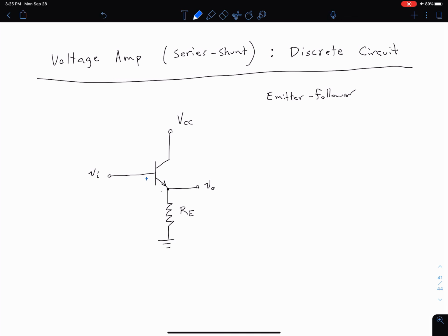So let's label, we have our base emitter voltage here, and notice I'm doing small signal labeling. So we can see in this case, our base emitter voltage is actually going to equal our error voltage. So our error voltage is equal to our base emitter voltage. And the only other voltage left if we're doing a KVL loop to relate our input, our error voltage, and our feedback voltage is this voltage across our emitter resistor, R sub E. So this must be then our feedback resistance.